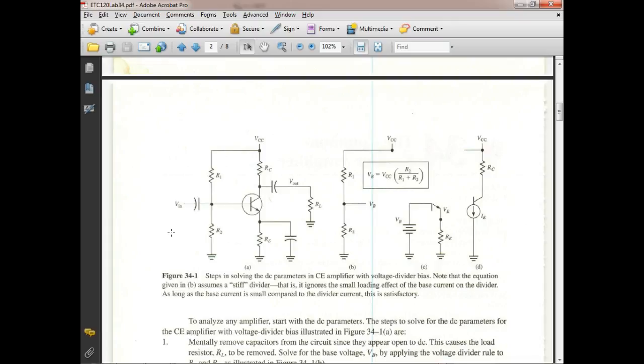How do you use an ohm meter to identify the cathode of a diode? We had two people say reverse bias it. That would be like me asking, how can I identify the cathode? I don't even know if it's good or bad. So how do we identify the cathode? You have to do two things. One way you measure overload, the other way you measure a junction, right? Y'all understand? We had two people say you put the black lead on the anode, you put the red lead on the cathode, and you measure an overload, and that's where they left it.